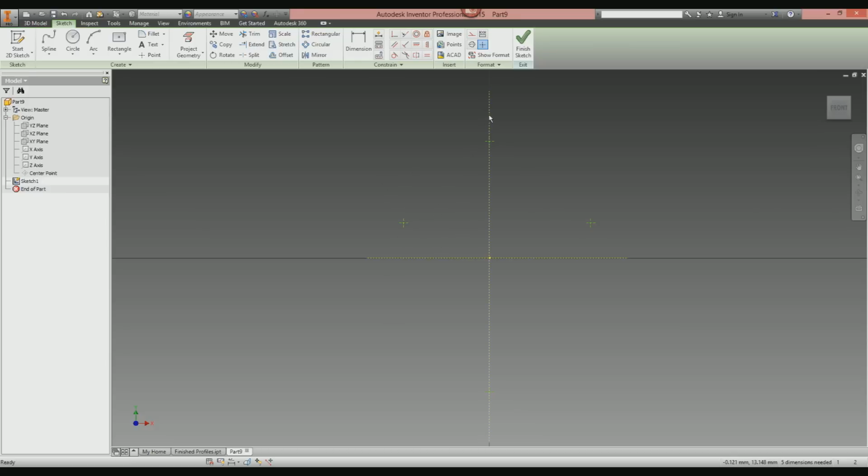So now that you've got this center line here, what we can then do is create a symmetrical constraint, which is this one here, and then pick these 2 points, pick that point, then that point, and then this axis, and then that will make these 2 points symmetrical around that axis. Great, eh? Right, you can do the same thing, symmetrical constraint between this point here, and then this center line here, and then that will do the exact same thing. Make these 2 points symmetrical around that axis. So now we've got that done.